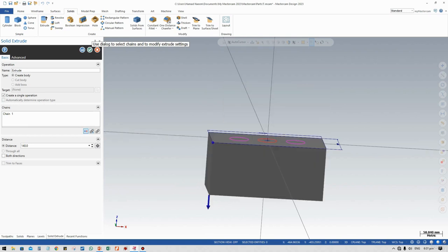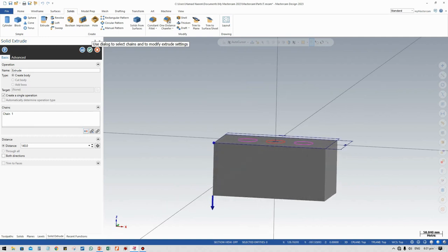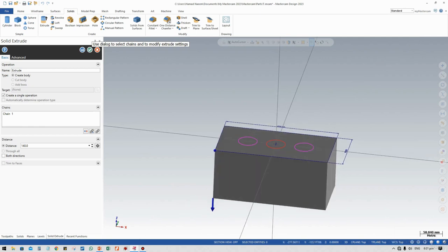Okay, reverse direction. I just want to create in the reverse direction because we want to create a geometry on the top plane. Okay, so we have the construction plane, top plane, and the tool plane is on the top, and the work coordinate system is also on the top side. So I just create 115 millimeter thickness and click OK.